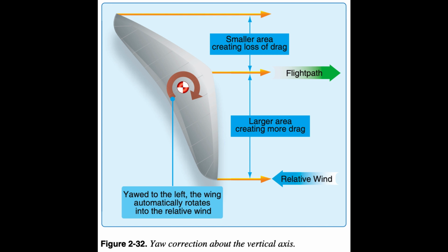The unique design of the WSC aircraft performs the same function through the swept wing design, but also the wing twist and airfoil shape from root to tip assists in the correction about the vertical axis. A simple way to understand the yaw stability is to see that any yawing motion is reduced simply through the increased area of the wing as it rotates about its vertical axis. Figure 2.32.